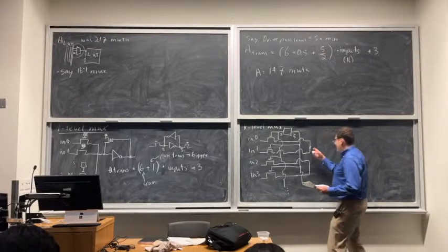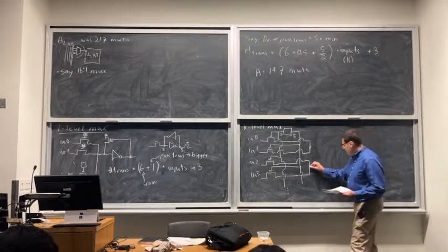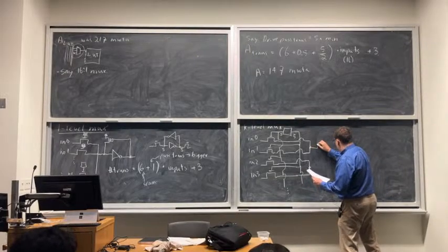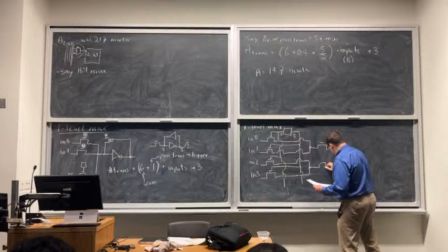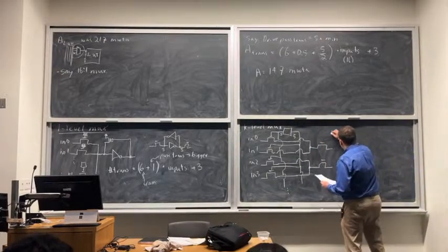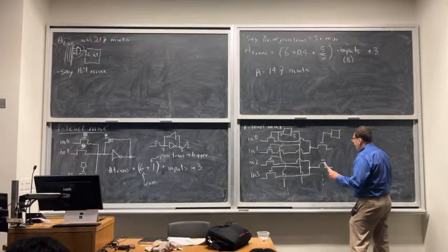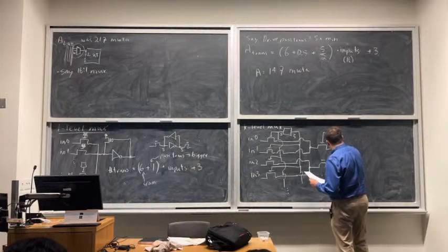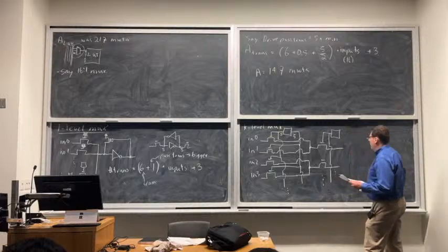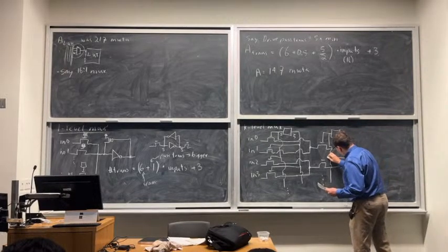Okay, so at this point, I've basically cut my number of signals in half, from 16 down to 8. So there'll be 8 of these intermediate wires. And then I just repeat the same style. So I take that, put it into a pass gate, take this, put it into a pass gate. We have 6 more down here that I'm not going to draw. And I make another SRAM cell. And that SRAM cell controls that one. And it goes down here to control some more. And the complement signal is going to go over here and control this one.